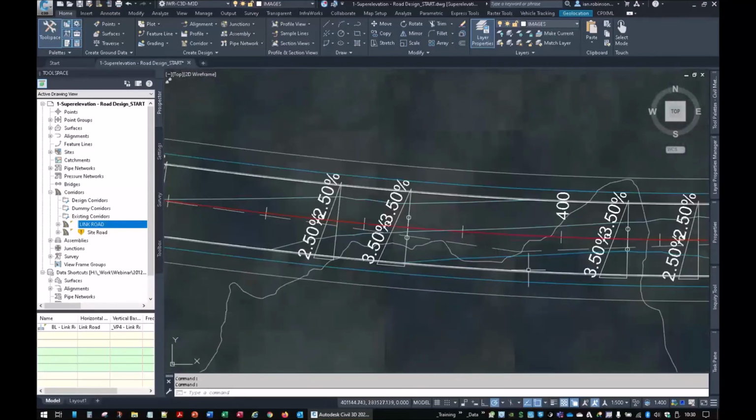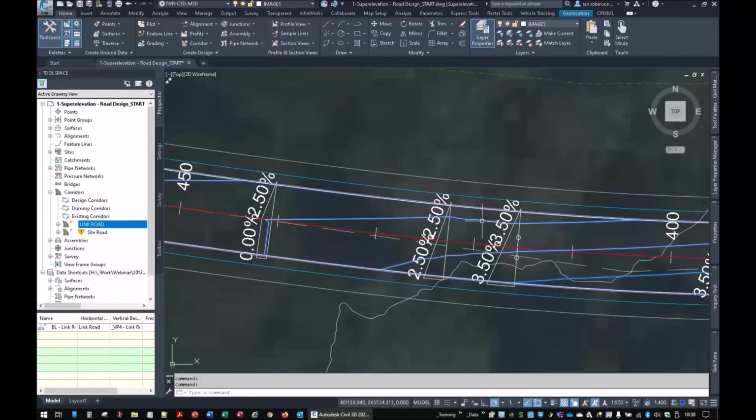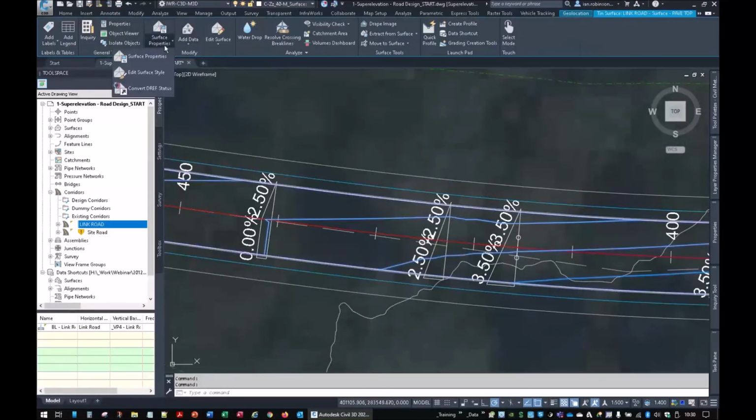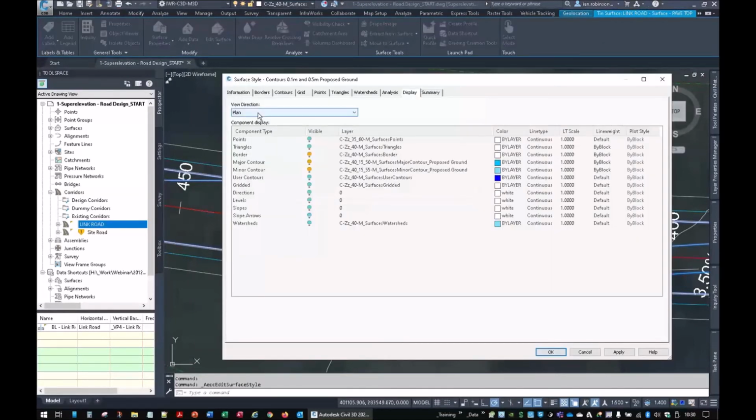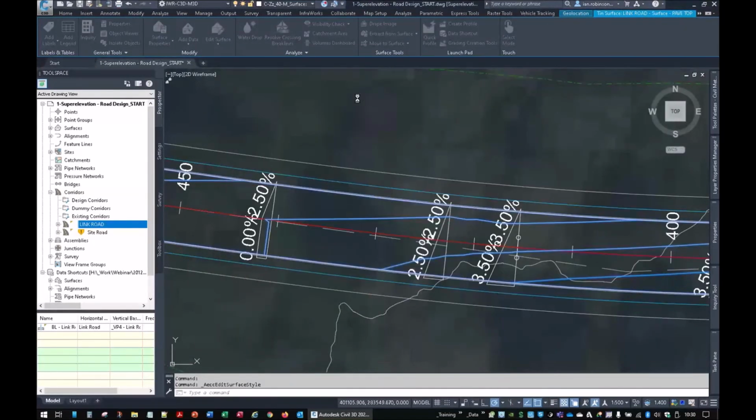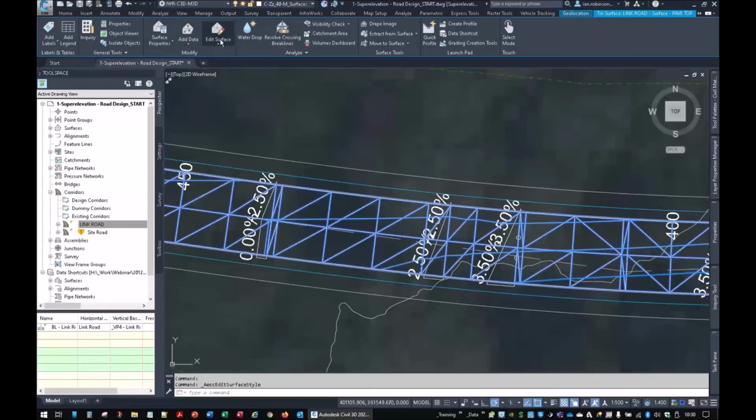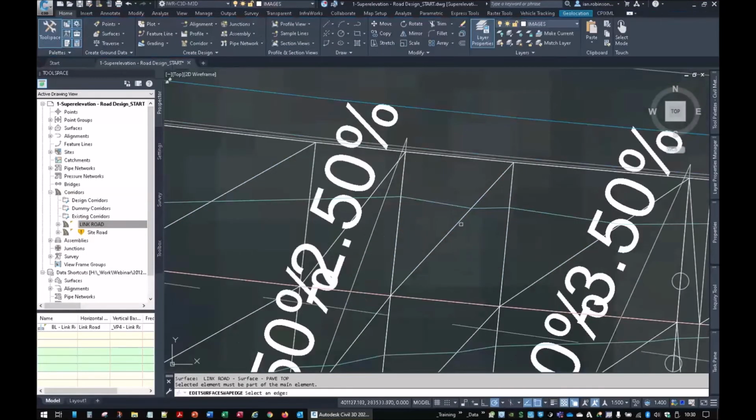Okay. If you do get wibbly wobbly contours, just edit them. So if I just turn on triangles, you can just edit them or just ignore them. Swap edges. So this one's a bit wibbly wobbly, so swap that edge. Let me turn selection cycling off like so, and we can swap these to give us straighter contours.